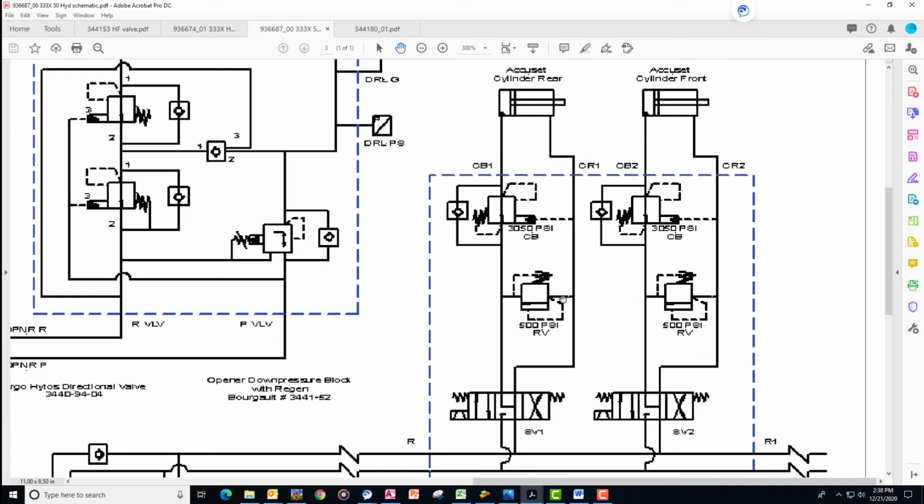That's to limit the amount of pressure that would sit on them when they're pushing against the shims, if there are shims installed. So it's effectively a relief pressure, so we cannot squish all the shims with the hydraulic pressure coming from the tractor. Then this counterbalance valve, all that it does is help hold these cylinders up during transport, so the weight of the QDA arms is not sitting on SV1 and SV2.